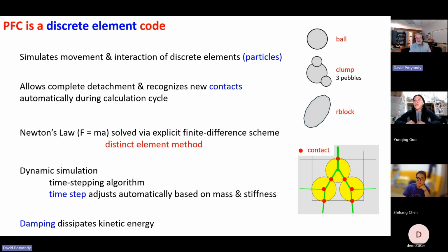You could say, oh, I have a superquadric, set the parameters, boom, now I know the shape. I'm going to turn that into a polyhedra. Boom, put it in as a polyhedra in PFC. Right? It wouldn't be exactly a superquadric because it would have these bumpy shapes, or put it in as a clump. It still wouldn't be exact, but it would do that. So that's basically the reason.